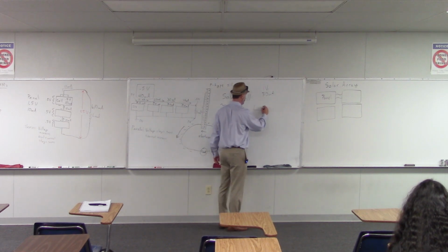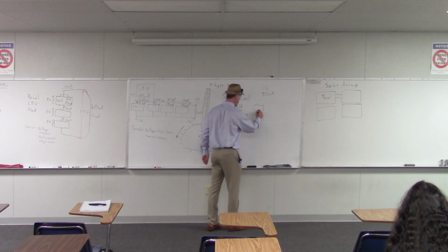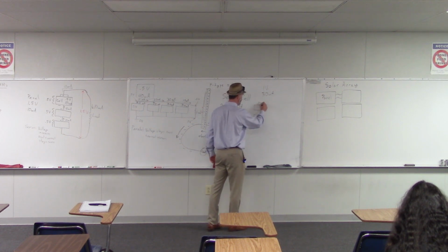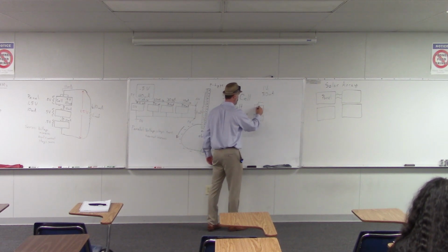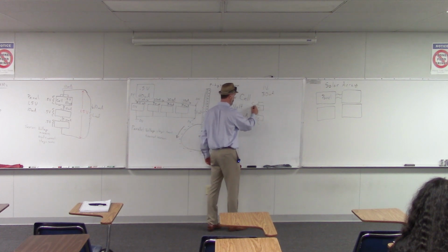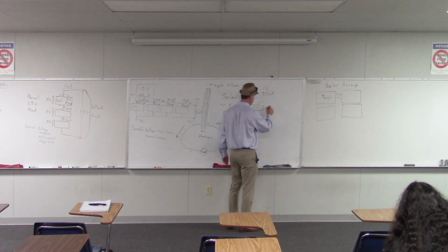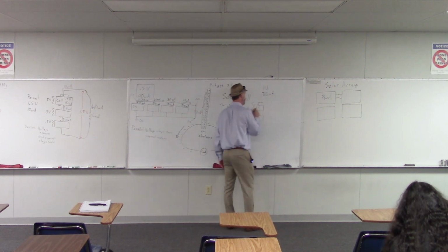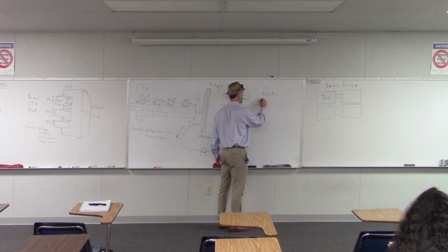So you could have cells in series like this. And so when you have 2 cells in series like that, each one is 0.5 volts, 0.5 volts. So together, this gives you 1 volt. And then if you put 3 of those in parallel, so this by itself is 1 volt and 10 milliamps.